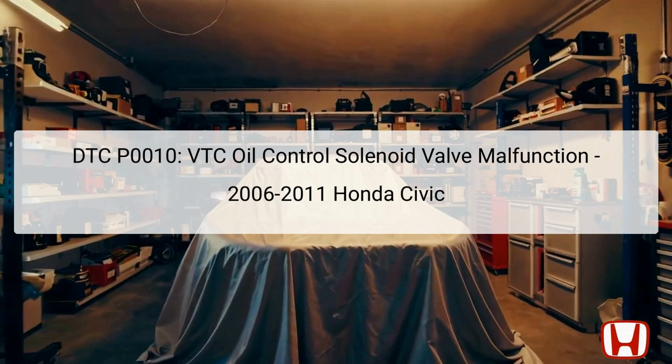You can typically find the VTC oil control solenoid valve located near the engine's camshaft, where it connects to the engine's oil supply. Proper functioning of this component is vital for the engine's operation, as it allows the variable valve timing to adjust according to engine speed and load, enhancing acceleration and efficiency. Addressing the P0010 code promptly is essential to maintain the vehicle's performance and avoid further complications.